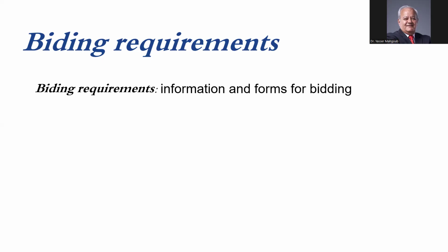Different types of delivery must be known from the beginning because they affect how we make the construction documents. So for each type of delivery, I need to prepare construction documents. If I have one single main contract, the whole thing will be one package. If I have 5 contractors, I need to prepare 5 packages and divide the work into 5.